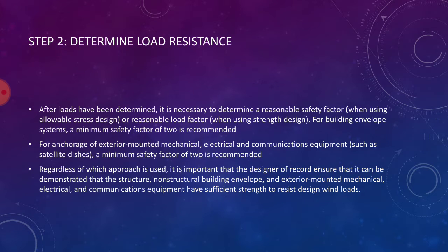Next, for anchorage of exterior mounted mechanical, electrical, and so forth equipment, such as your satellite dishes, a minimum safety factor of 2 is recommended. And as follows, regardless of which approach is used, it is very important that the designer ensures that it can be demonstrated that the structure can withstand all of this wind pressure.